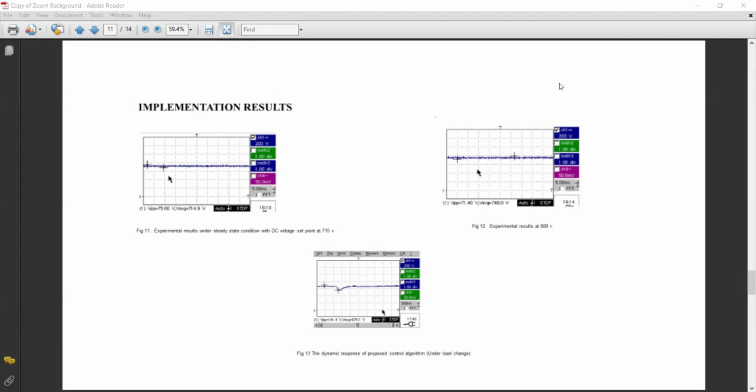The results indicated that the maximum instantaneous error is very small and consequently reduced. Hence, it is concluded that the proposed method yields a steady state error closer to zero. And from figure 13, we can see the voltage ripple during full load operation. In the worst situation, that is full load operation, the voltage ripple is less than 3%, demonstrating the enhanced effectiveness of the control strategy.